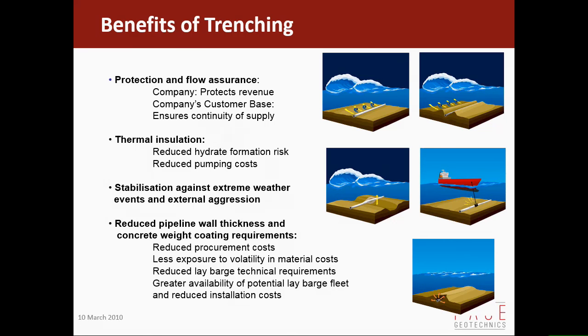What are the reasons for trenching? Well, protection and flow assurance. Obviously, by putting the pipeline below the seabed, you're protecting it from certainly fishing gear. Fishing gear is very rarely designed to penetrate to any depth into the seabed, but also ship's anchors, which is a much more aggressive form of thing. And if a ship's anchor hits a pipeline, it could well rupture the pipeline. So by doing that, you're protecting it.